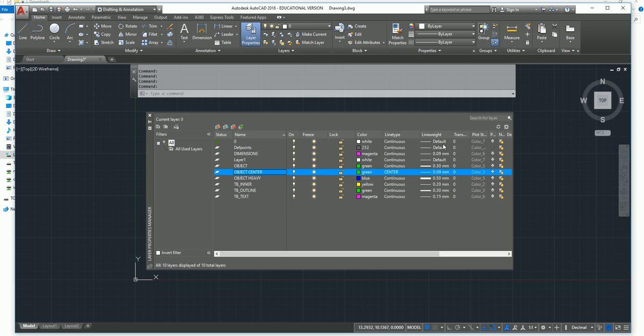We'll get into that, especially when we get into some of the presentation drawings like the elevations, so you can start reading what's closer and what's further away. The floor plans will be the same thing. Your dimensions, you never want the same thickness as your wall because you want to be able to tell the difference, or your object in this case. I'm just calling it an object for now because the first thing we're drawing is just a part of something that I made up.